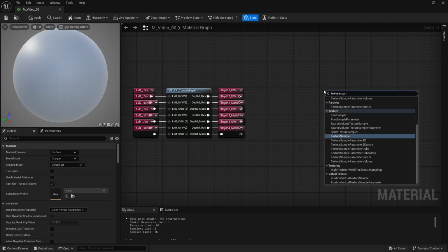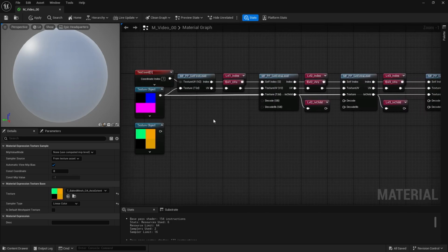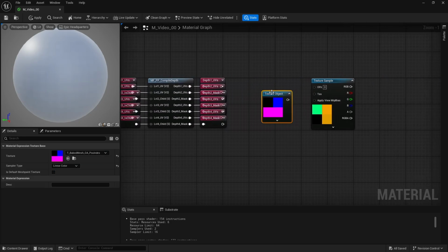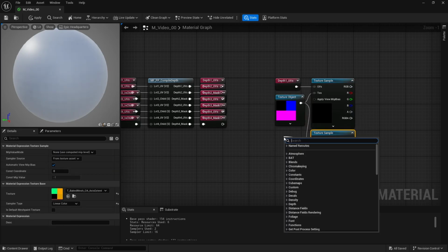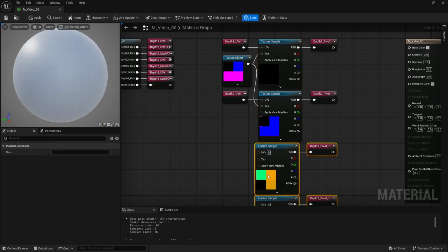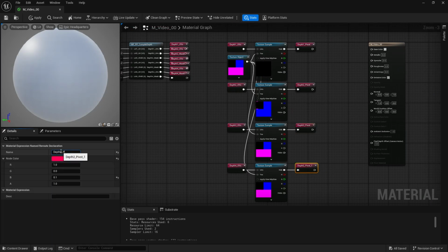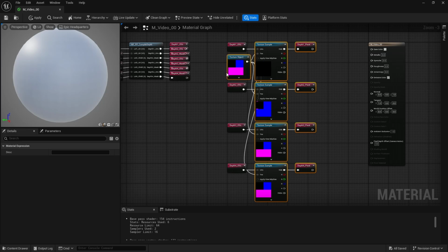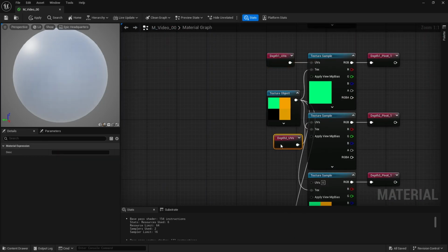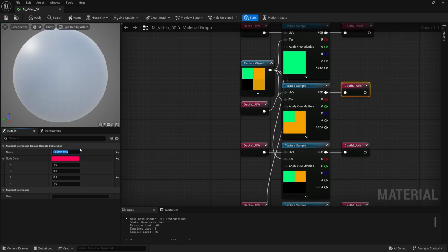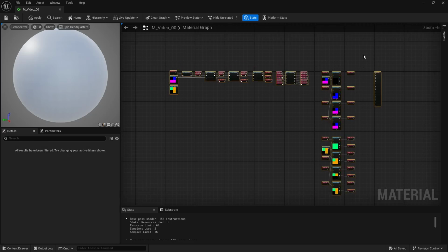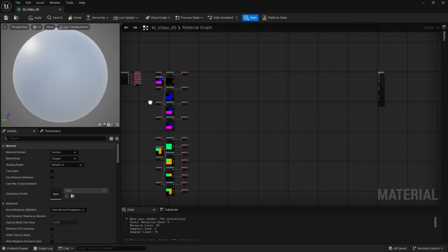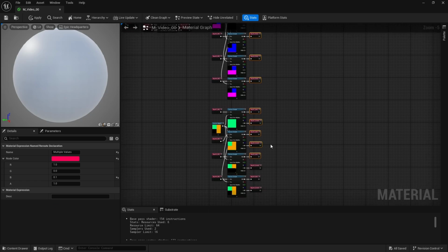We'll sample the position/indices texture 4 times, once at each depth level. I'll fast forward the process of wiring those and creating the corresponding named reroutes. Then I'll repeat the same process for the texture storing axis and extent. Now I have everything I need to start manipulating vertices in a way that mirrors the hierarchy we set up in Blender. It's not super straightforward, so bear with me.